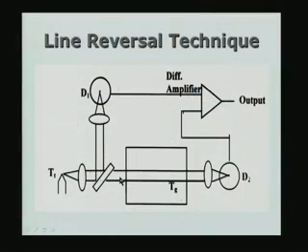From the target we have a monochromator which will allow only light of the correct wavelength, for example, in this case sodium emission wavelength, so that you are looking at that part of the spectrum alone, and the D1 will give you the direct view of the target, and the D2 will give you the signal corresponding to the view through the gas. And when the two detectors give you an output equal to 0, then we know that the temperatures are the same, and of course, we have to calibrate the target by having the temperature measured independently for the target. So, whatever target temperature we measure is actually the gas temperature.